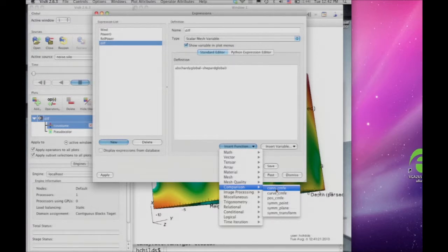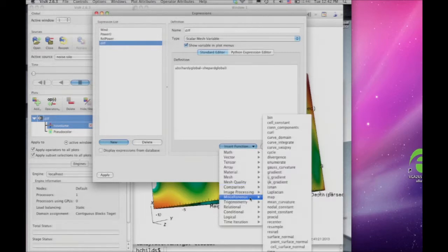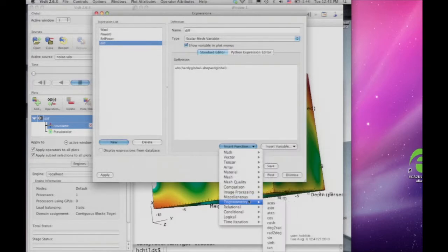And you can also get statistics about it. If I change the display to just the connected components related queries, I can ask for the volume of each. It'll tell me there are 15 components and what the volume of each component is. If I wanted to, I could isolate these components and start doing separate analysis on each component.